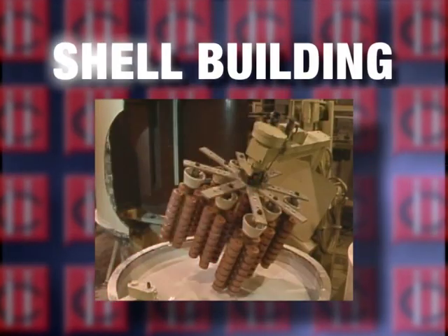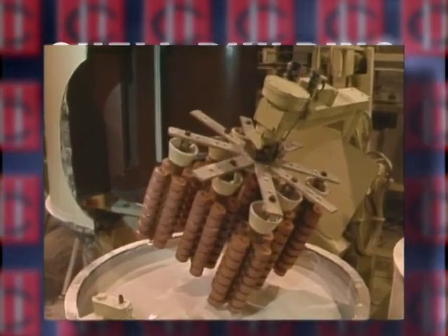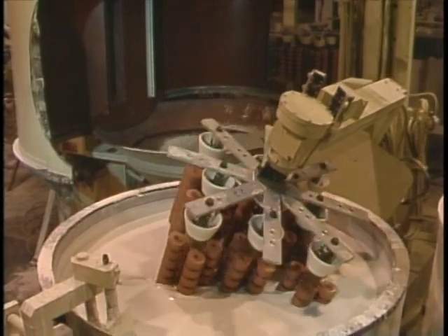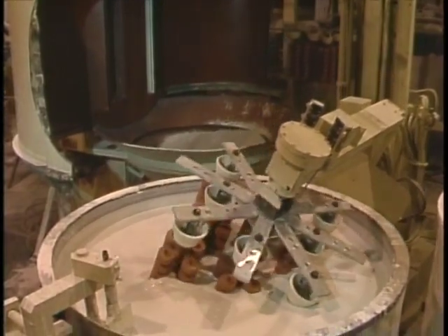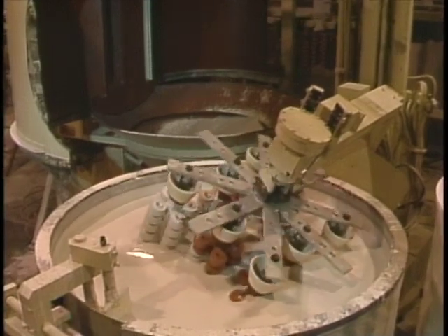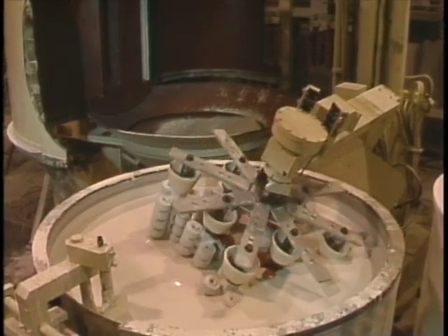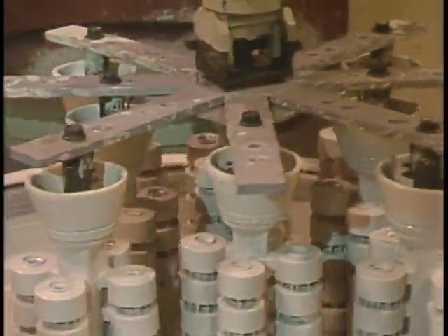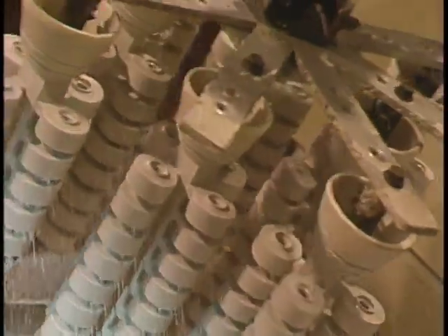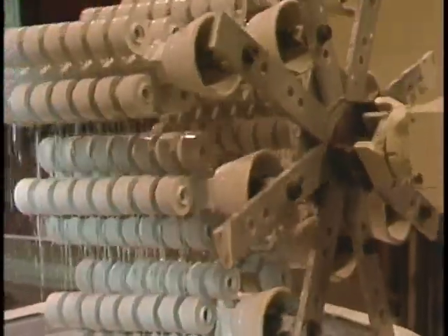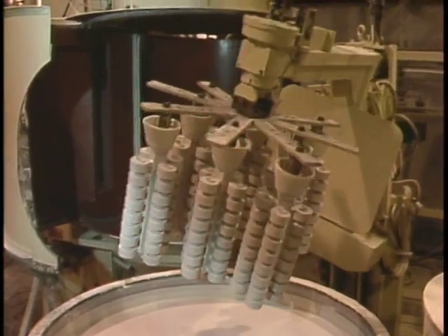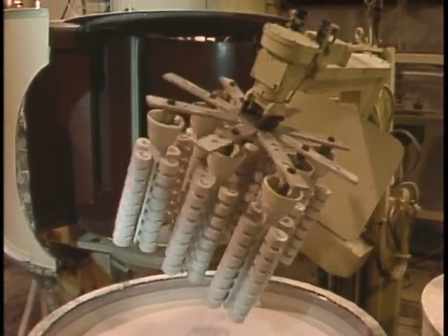The completed assembly is then processed to produce a ceramic shell mold. This is accomplished in several stages. First, the wax assembly is dipped into a cleaning or etch bath, and then pre-wet before it is dipped into the first coating of slurry. This is a critical step in the process, for the operator must produce an almost flawless coating upon which to build the shell. The assembly is carefully examined, and any bubbles in the coating are burst with an airstream.